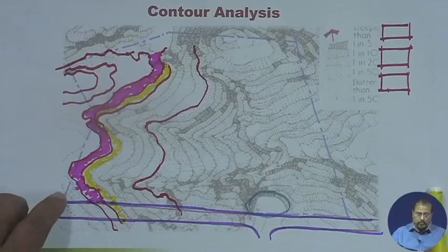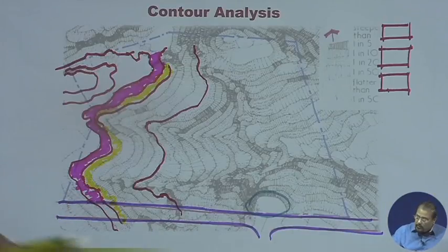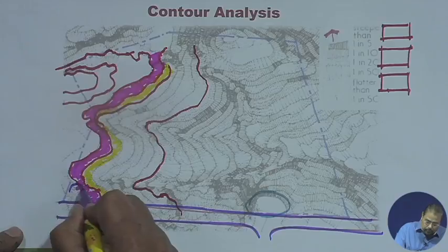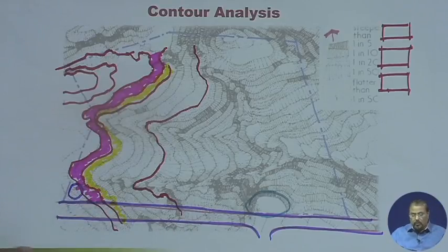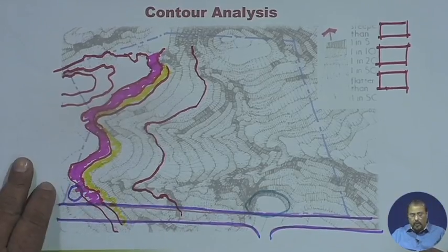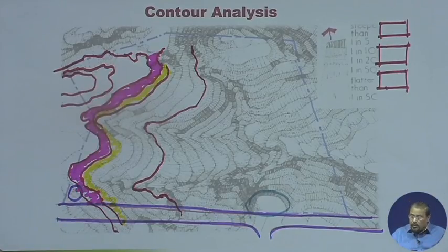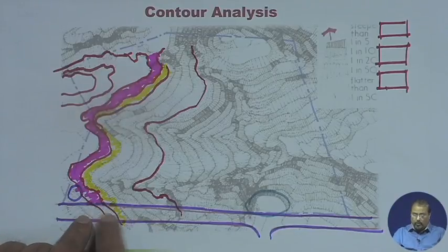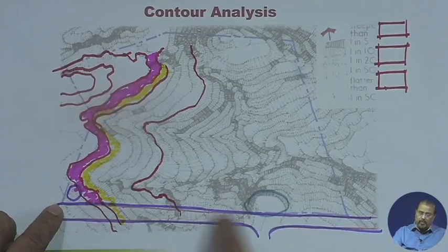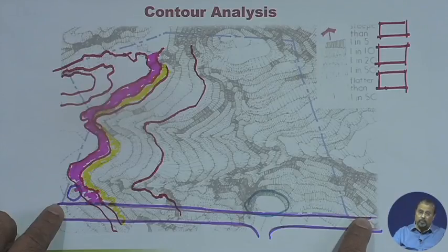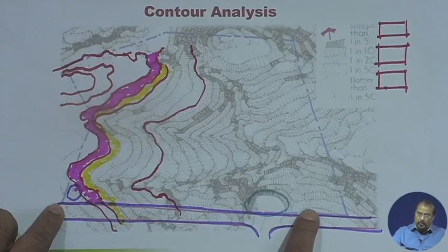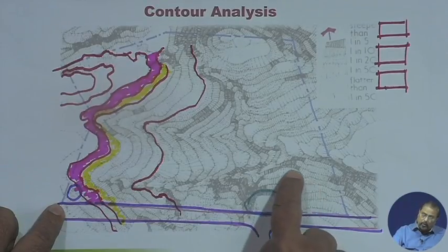Now, in this case, the overhead tank's best location is this. Then, if this is the overhead tank location, where should be the position of the cottages? Now, cottages, how do you locate? Cottages you locate with the best accessibility. Here, I find that from this particular edge, every part of the edge has equal potential for accessibility. But since this is the lowest point, if I have the access to the site from this particular point, then one has to go all along.